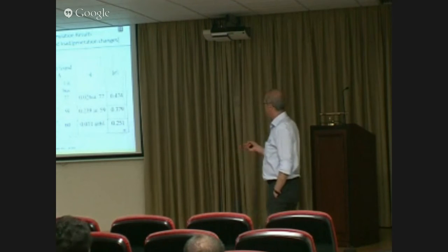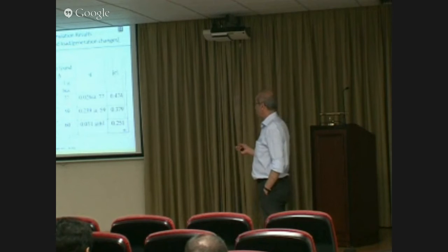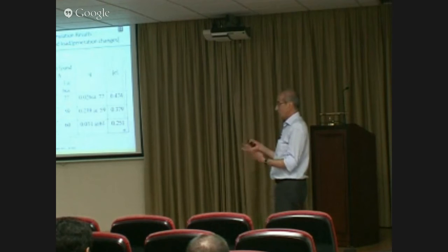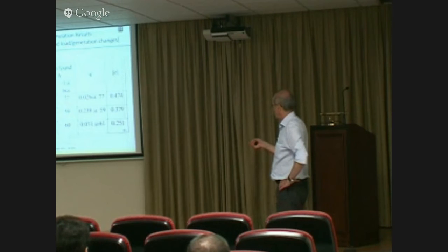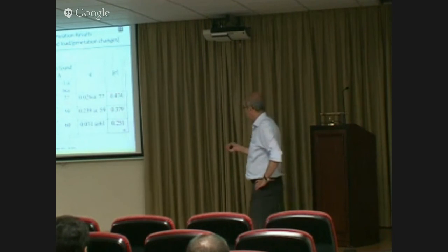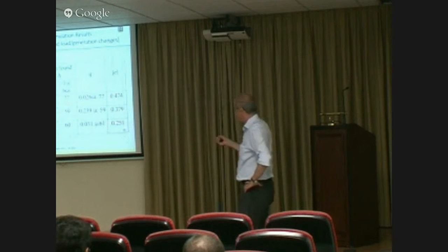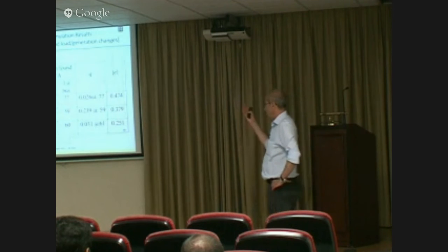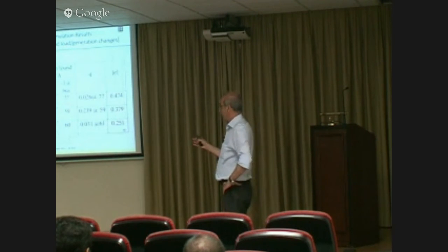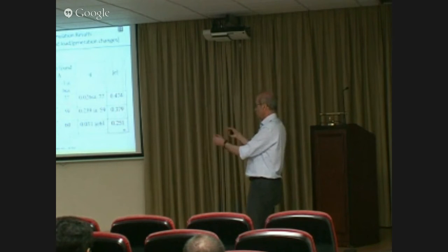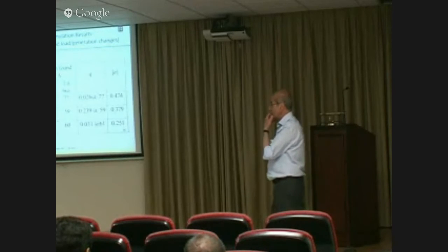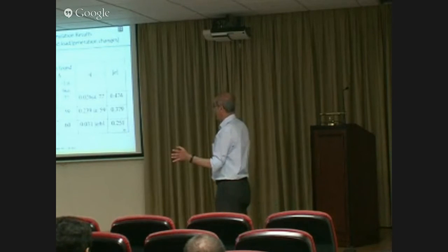And then now, if you further go and introduce slowly changing loads or generation, which is the more realistic case in an actual setting, then you also see errors. So here we notice that in addition to these, we also get errors because the remaining variables in X are not going to be exactly zero, because there are some load changes. Therefore, you see these small changes in injections in every bus. But those injections we assume to be small compared to the outaged line.